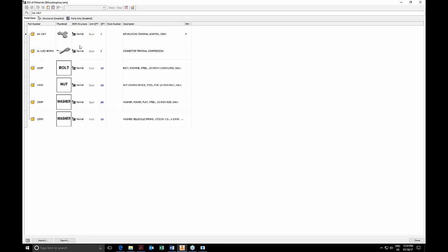So here in the bill of material, we can see that I have two normal parts, and then I have four empty parts. I call these empty parts. All they are is for bill of material purposes. So it just brings in the information there without bringing in the heavy weight of having another part and having all those lines drawn whenever you do a drawing and such as that. Because most of our stuff is viewed from 5 miles away, right? You've got that long range view. Rarely do we come up in close detail, and when we do, we could do something special for that.